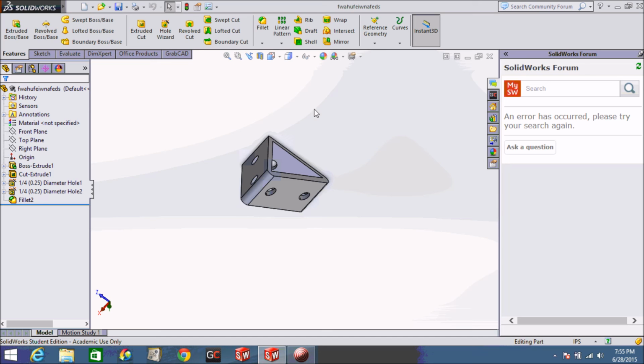Next, I have Smart Dimension, once again bound to A. You can have multiple keys bound to the same function. Extrude bound to S. Extruded Cut bound to D. And Hole Wizard bound to F. So this means that when I'm working in the part context, I have all of my basic extrude, cut, and hole wizard functions bound to the home row four keys, ASDF, and that way I don't have to move my fingers around when I'm working in the part context.